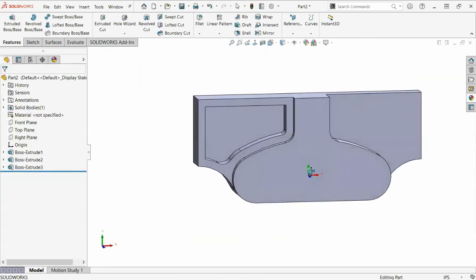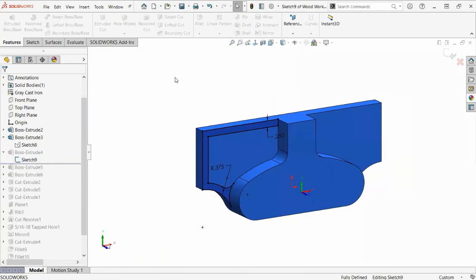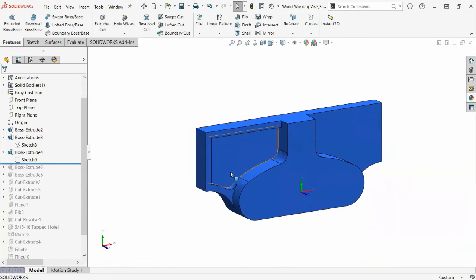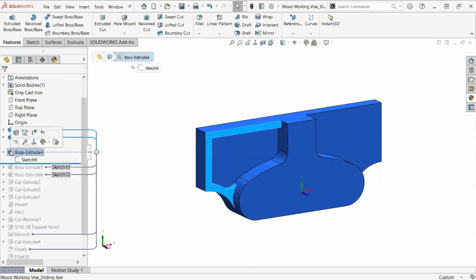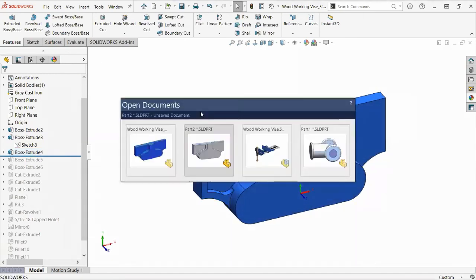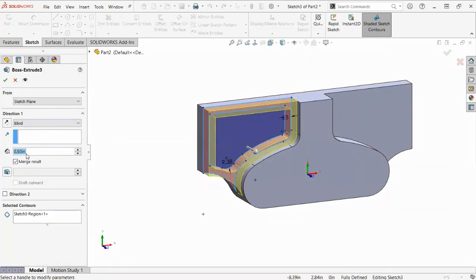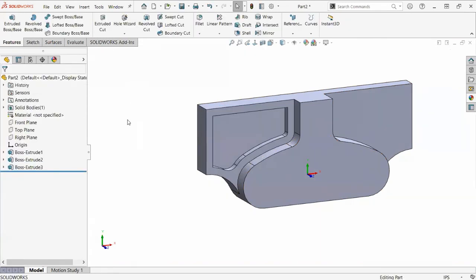And we're moving and grooving. Things start to take shape here. Let's go back and look at our example. We'll exit that without making any changes. Oh, it looks like I extruded it too far. So I can double click to check the extrusion depth, and that is 1/4 inch. I can modify that, no problem. All right, let's continue on.